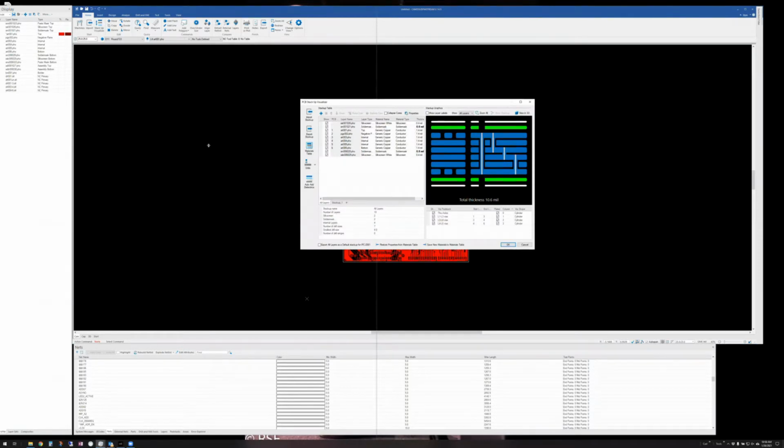And I just wanted to show you a couple more things. If you go to layer sets, this is where I set those layer sets, and you can actually turn on the layers that make up those layer sets. But reality is all that's done in the loading process now, and what controls that is something called the stack-up visualizer. And this is what I mentioned early on, is that I can have the dielectrics in there. I could change dielectrics.